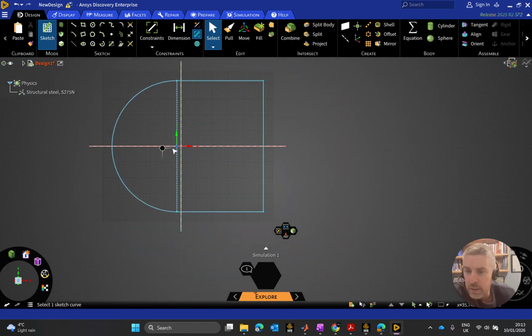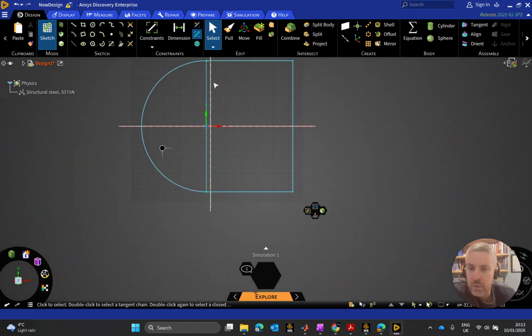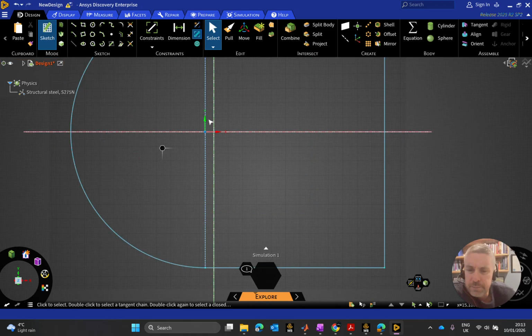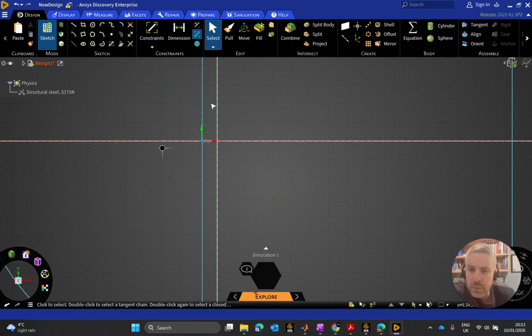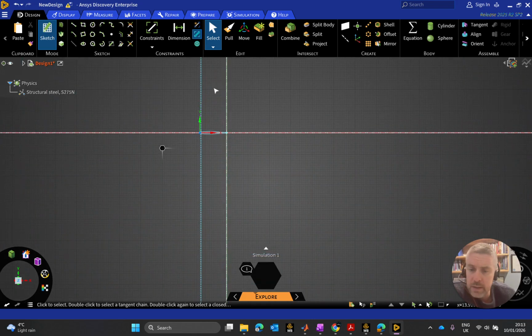Why so high as well? A lot of people might ask that. How come you have to go 15 chord lengths up? Well, the fact of the matter is, there will be effects far off of the airfoil, and that is also part of this kind of pinch idea that often comes in when people try to explain lift of airfoils.